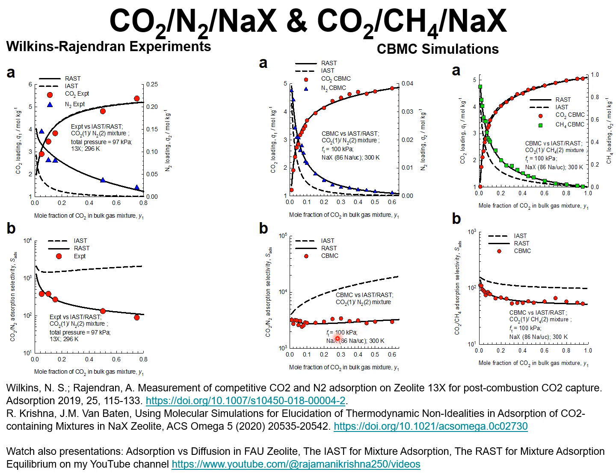A precisely analogous situation holds for adsorption of mixtures of CO2 and methane in NaX zeolite. The CBMC data show that the IAST overestimates the CO2 methane adsorption selectivity to a significant extent.